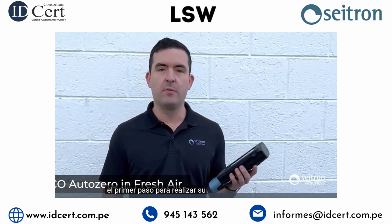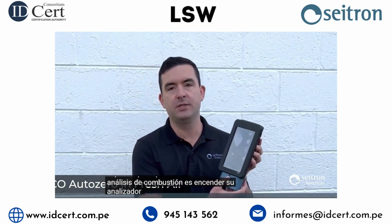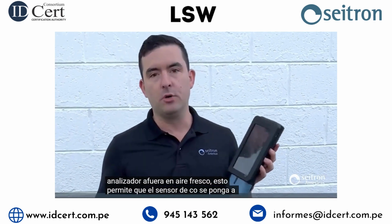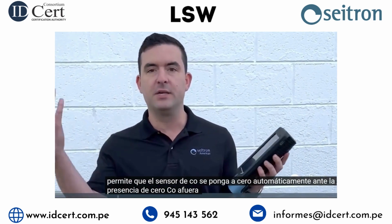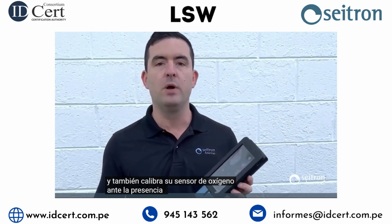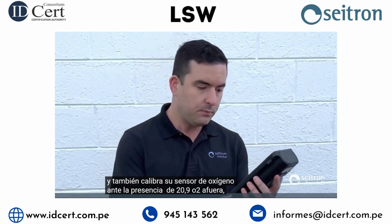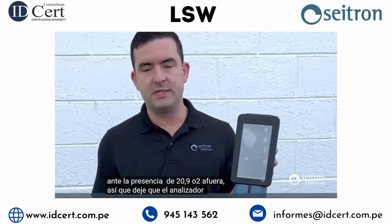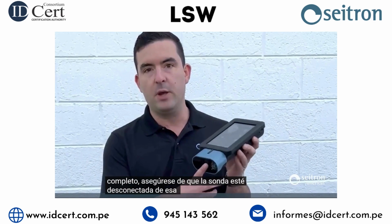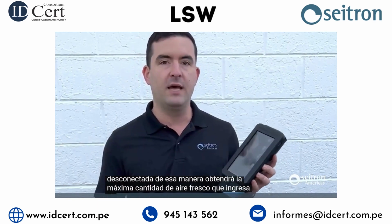The first step to performing a combustion analysis is to turn your analyzer on outside in fresh air. This allows the CO sensor to auto zero to the presence of 0 CO outside in fresh air, and it also calibrates your oxygen sensor to the presence of 20.9% O2 outside. So let the analyzer run through its 60-second auto zero cycle till it's complete. Make sure the probe is disconnected, that way you get the maximum amount of fresh air going into the analyzer.